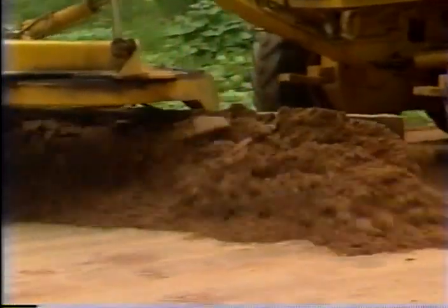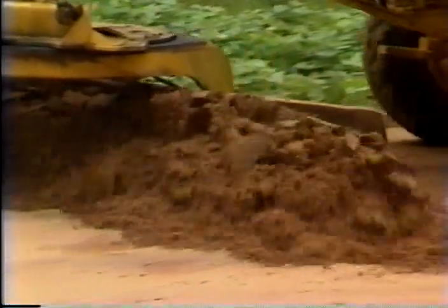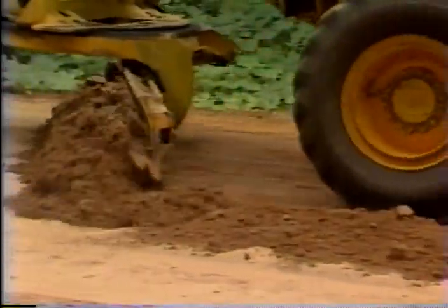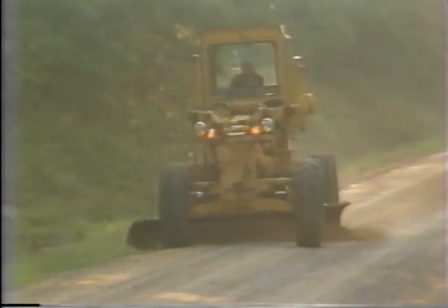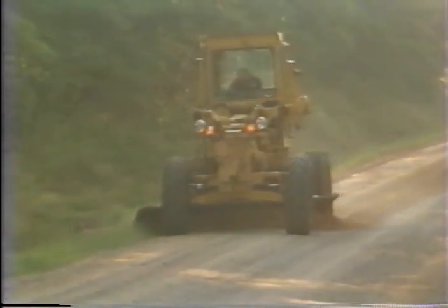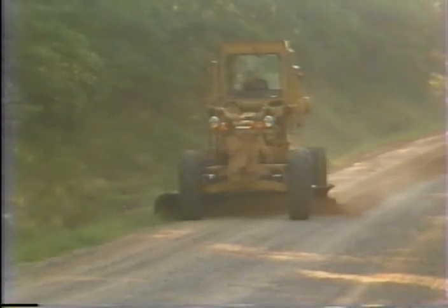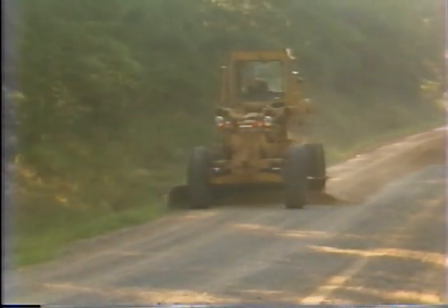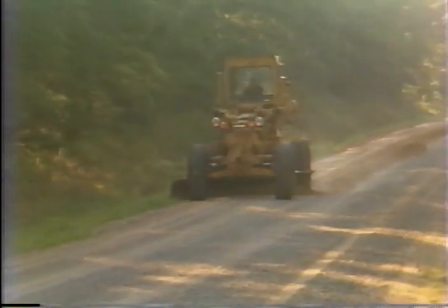A backward pitch is used for cutting or reshaping of the road. Use backward pitch in conjunction with enough downward pressure to create a cutting action. The majority of jobs are performed with the blade in an upright position or tilted forward slightly to get a mixing and compacting action of the material.